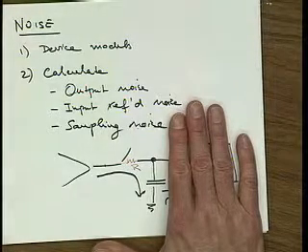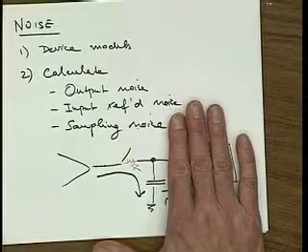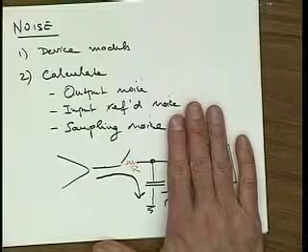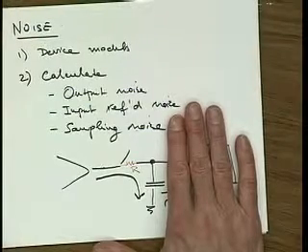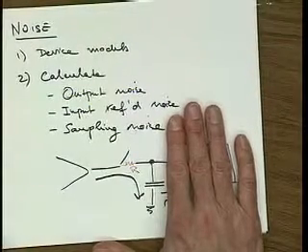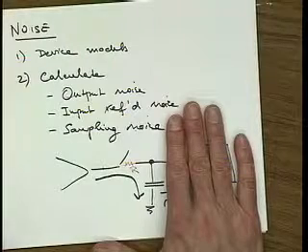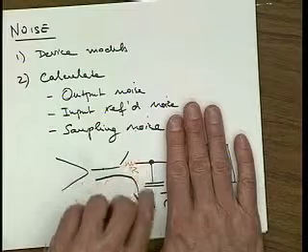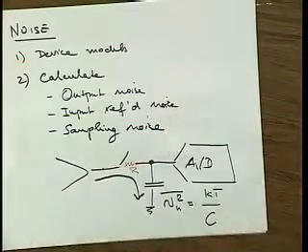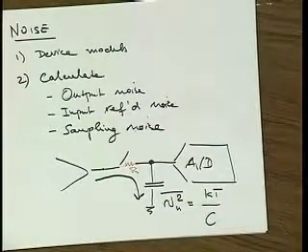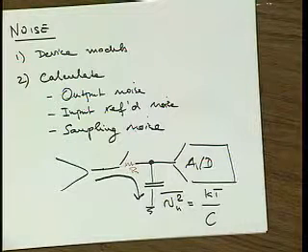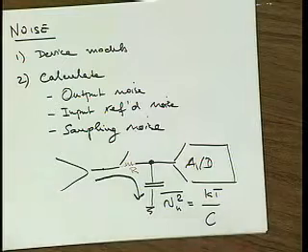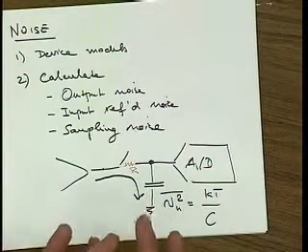If you look at precision, or how much gm or how much efficiency we can get, well, bipolar or maybe even other more esoteric technologies always win. But it's this simple thing that with CMOS we can easily fetch a signal, store it onto a capacitor, and then do more computation with it. That turned out to be an extremely powerful thing that compensates for all sorts of otherwise deficiencies of CMOS.